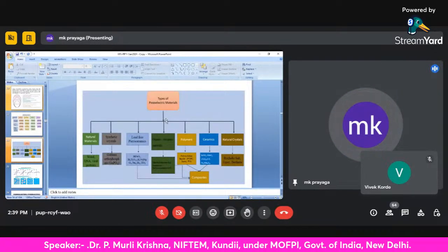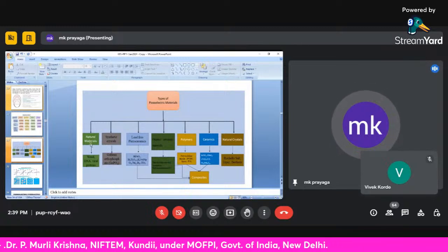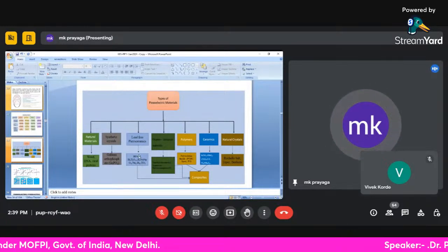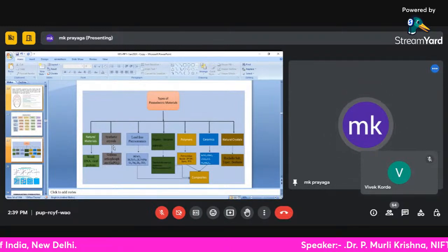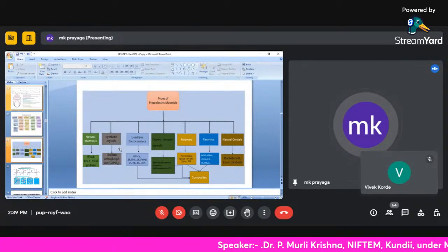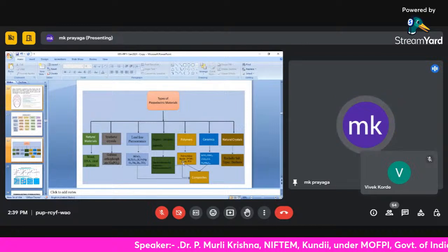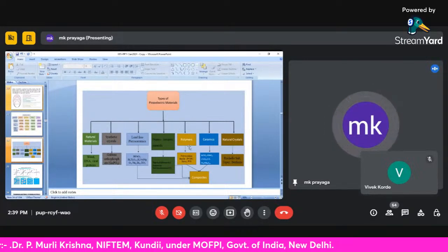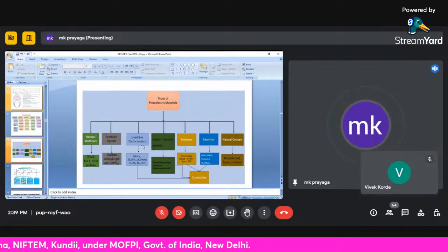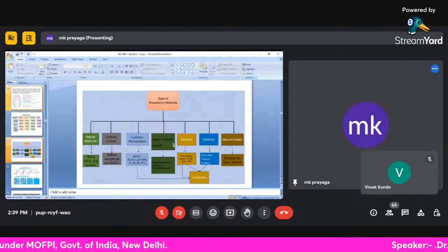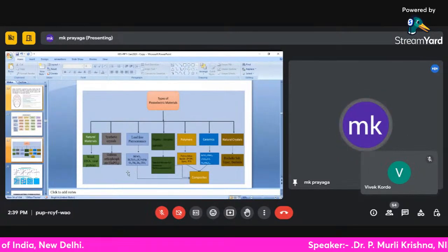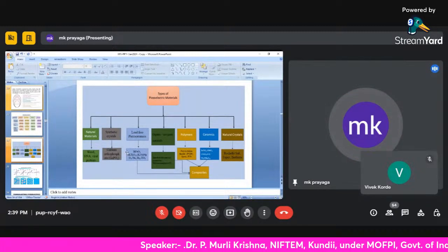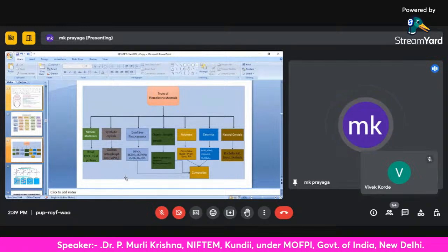And of course, again, these are the types of piezoelectric materials. We even have natural piezoelectric materials. But for materials synthesized in the lab for your particular applications, you have to develop composite materials using a combination of materials. Either you may take polymer into ceramic or lead-free material into polymer. With that combination, you can design and develop the material. And in these synthetic materials, people are nowadays even working with gallium orthophosphate.